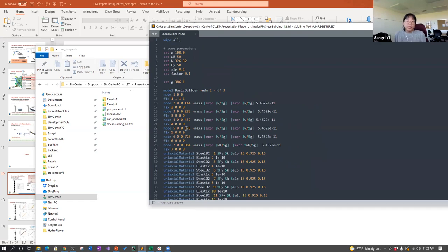To make this script interface with quoFEM, you have to consider two things. First is input and second is output. First, you have to let quoFEM know which are the random variables among all the variables you have. For that, we have a command called pset. We can use pset instead of set, and then quoFEM will detect this command and consider it as random variables. And that is all for the input part.